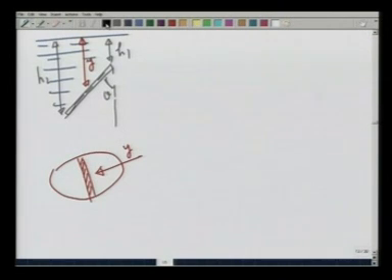So the net force F is going to be equal to rho g times the integral of y dA, where dA could be a function of y, because the shape of the plate or sheet could change according to how deep you are from the water.